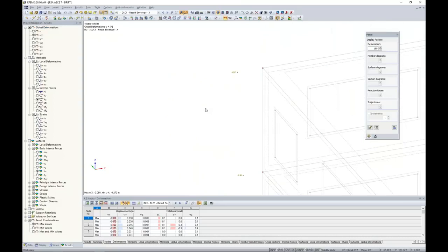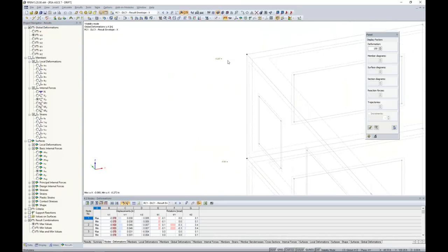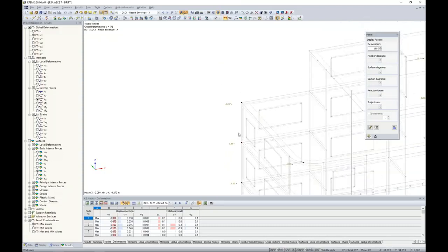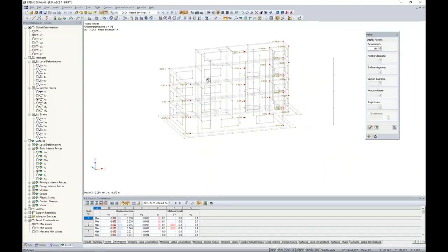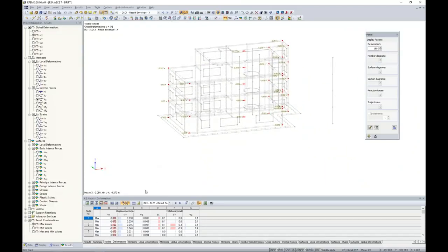We can zoom in here to an edge point, let's say, and the deflection here for our top story is given as 0.207. Well, the story below it is 0.161, but don't forget that we do need to multiply by the C sub D factor, divide by the importance factor, which is what the code tells us. So an easy way to pull all this information of only the relevant nodes we're interested in is to create this user-defined view. I can highlight all of my elements here, so you can see they're selected with red.